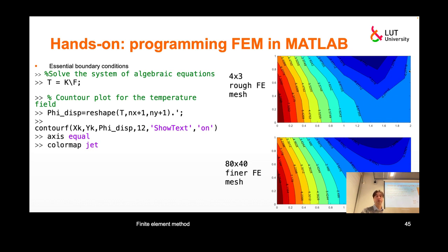It's quite a non-smooth shape. This is basically because it represents the idea that we have linear interpolation of temperature within each element. So those are literally linear isotemperature lines, because of that linear interpolation. You can see the consequence of the assumption that within each element temperature varies linearly with respect to coordinates. We can clearly see that.